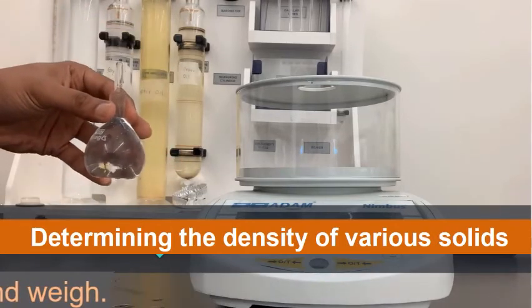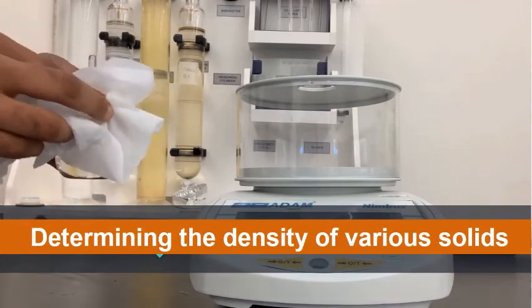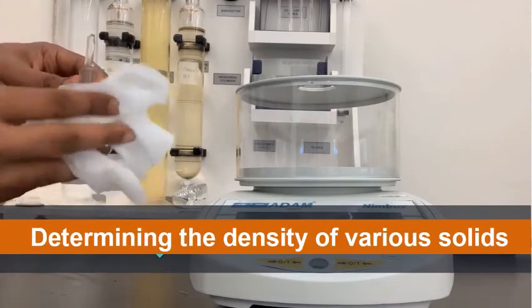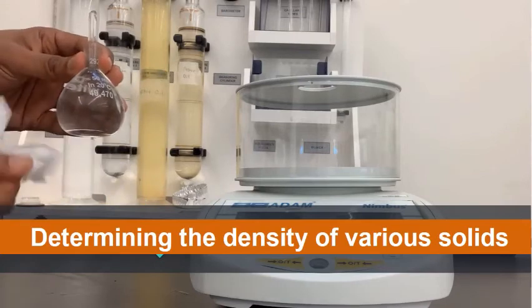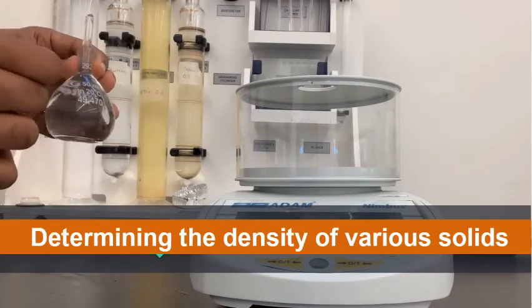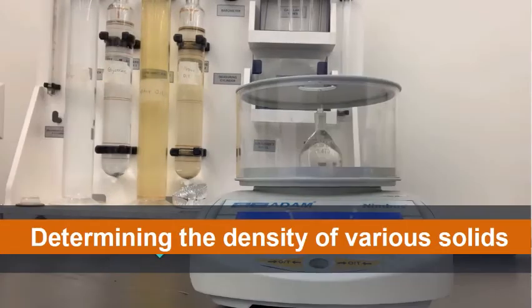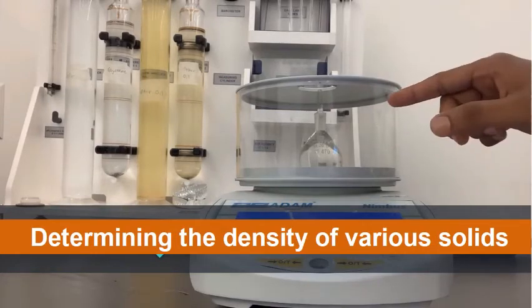Then we will remove the excess water and make sure that there are no bubbles that form inside the pycnometer. Then after this, we also take the mass of this pycnometer with water. Then record the data.